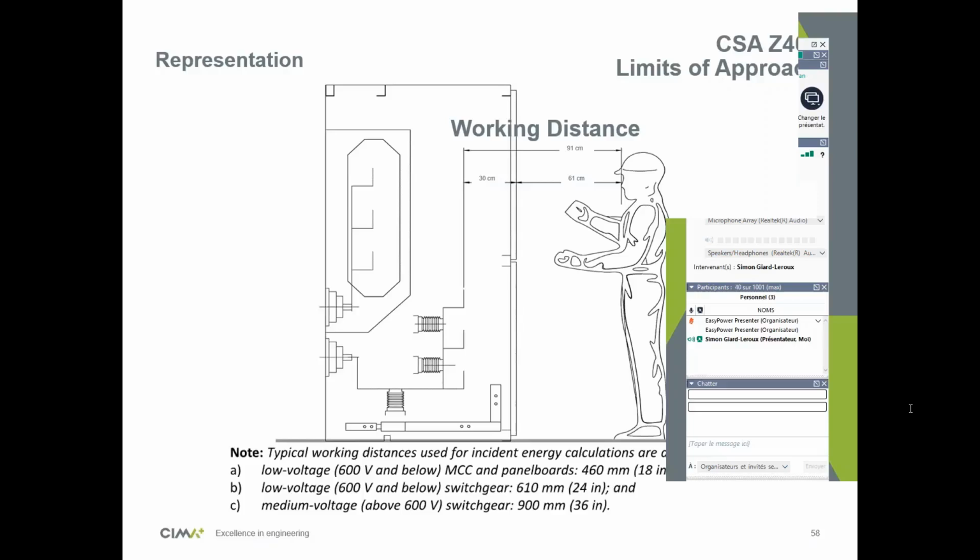Then another question from Jim. What about equipment fed by a 125 kVA transformer, arc flash calculations and less than 240 volts, CSA Z462? This limit was changed in the IEEE 1584 2018 version. The 2002 version stated that arc flash assessment was not necessary under transformers below 125 kVA and under 240 volts. But now this was replaced by under 240 volts and under 2 kA of available short circuit current. So the IEEE 1584 standard states to cut off your arc flash study at 2 kA short circuit. If you want to consider equipment lower than this, you can, but the standard does not require it.